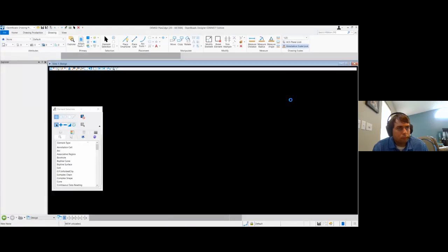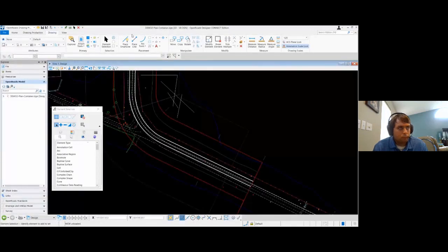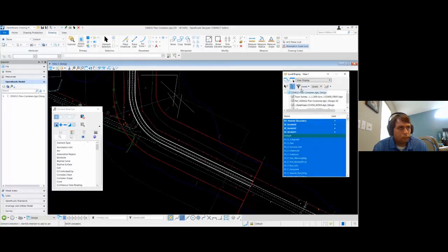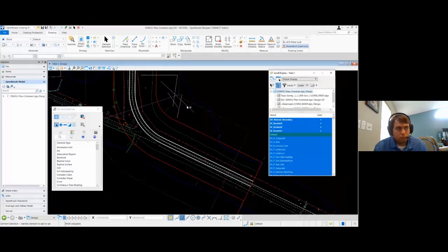and I'm gonna start changing level display, but I'm gonna do it globally, and we can see how it works with the variable off. So in my level display, global display here. Now I added these couple things right here to start showcasing this because remember the display overrides only affected nested references, so I drew some stuff directly in here to show what happens with the direct reference. All right, so what I'm gonna do is turn all those three off globally here.